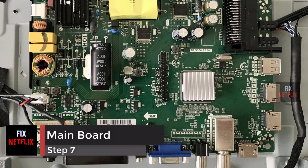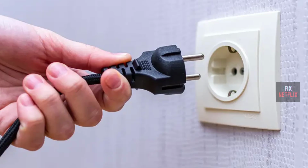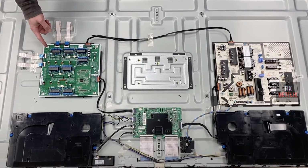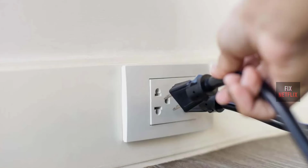Step 7. Main board. Now we check the main board to see if it is the culprit. If a problem shows up on half the screen or only a portion, it is likely the main board rather than the T-con board. Make sure the TV is unplugged. Plug in the cable running between the power board and the main board, which was disconnected in the previous procedure. Then plug in the TV.